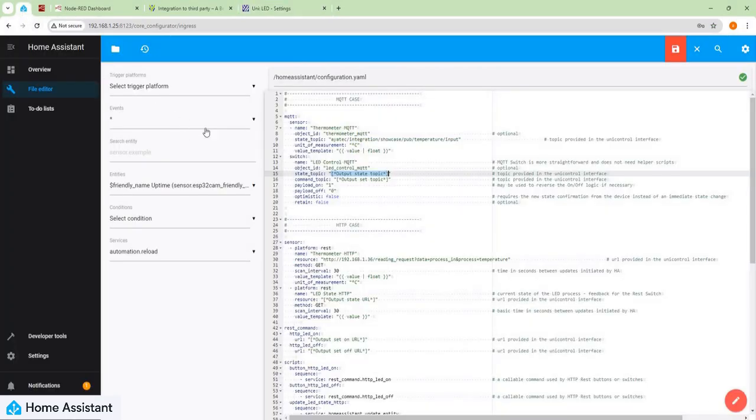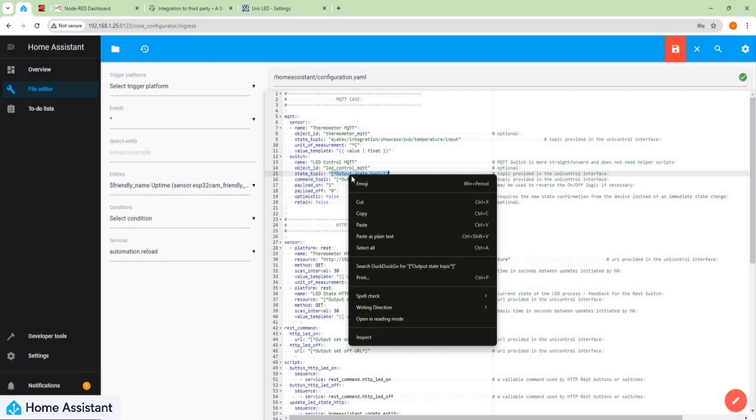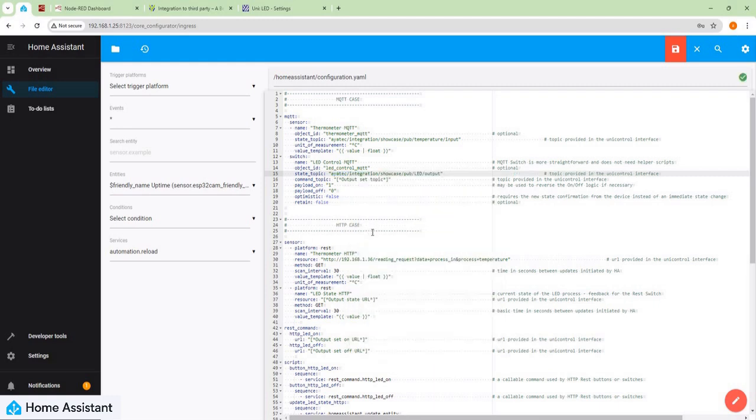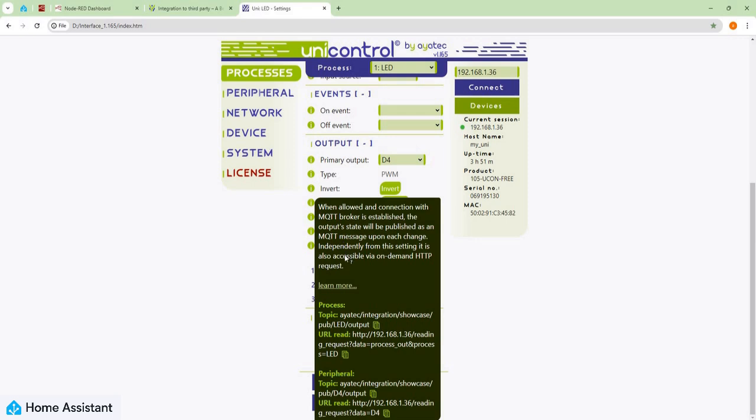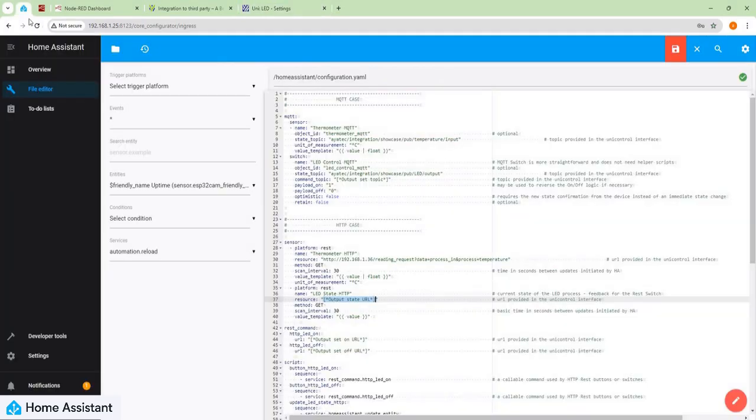Be careful to select the process variant that follows the intuitive logic where 1 stands for the LED being on and 0 for off. In this specific case, it is inverted from the real behavior of the ESP8266 onboard LED, which glows when the D4 pin is low and turns off when it is high.